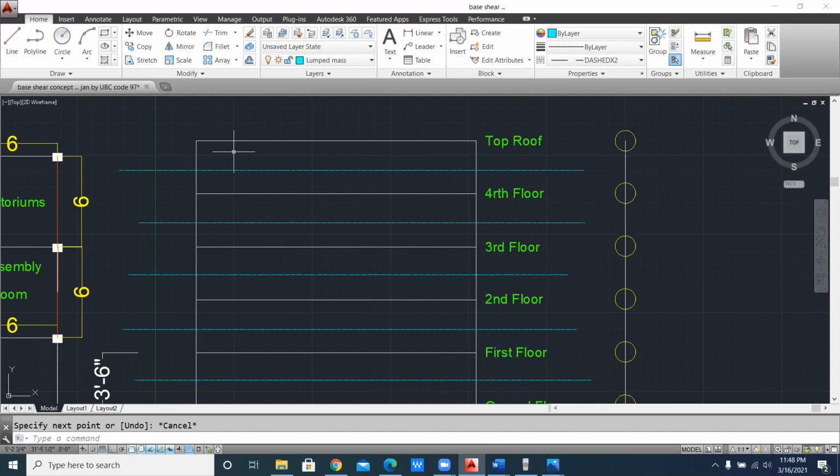Whereas for the top floor, only this floor is left for this value, so normally you have to take 1.75. You don't need to subtract anything, because it is the top floor. You have to do this separately on its own. I did not consider a top roof. I did it only up to the fourth floor, because it would take more time for our topic.